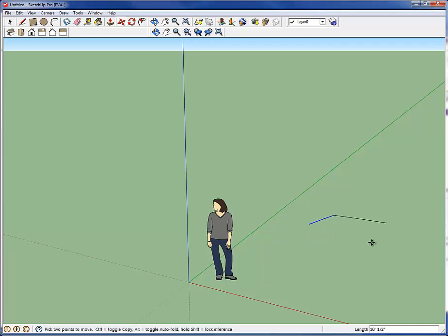And the other really important thing that you need to pay attention to is that SketchUp utilizes what they're calling an Inference Engine. Essentially, it works kind of similar to Revit in that it automatically constrains the model geometry to other model geometry. It's kind of a double-edged sword.